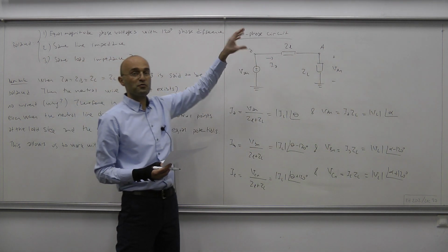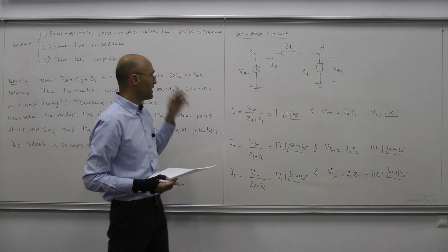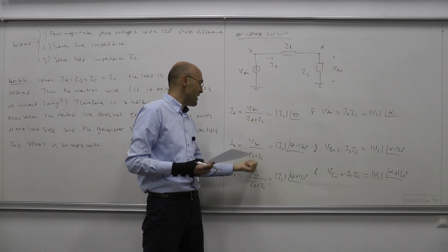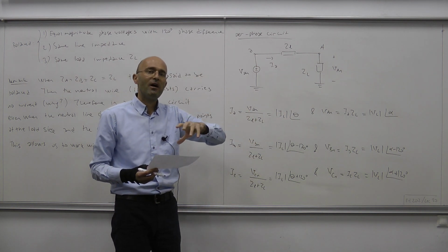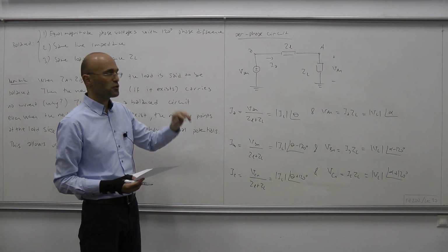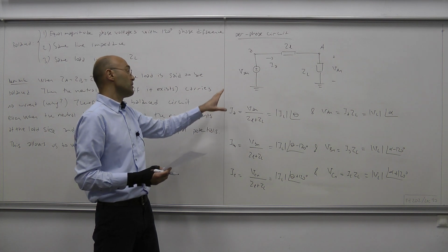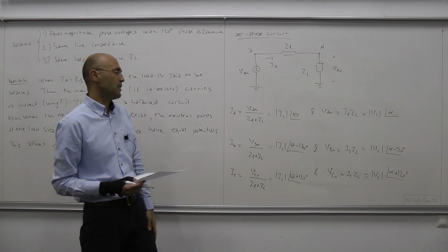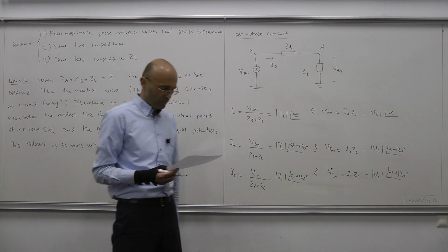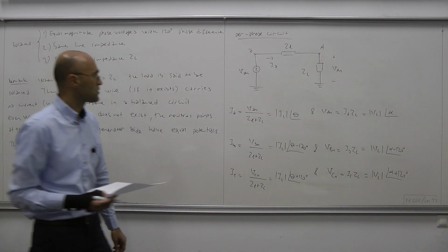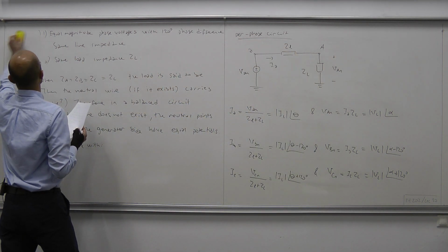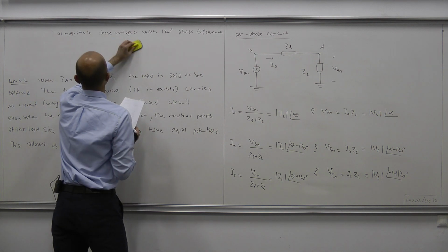Therefore, because we're dealing with a balanced circuit, the balancedness of the source voltages VAN, VBN, VCN will be shared by all the triples, be it current or voltage, throughout the circuit. So the balanced phase currents will have the balanced phase voltages on the load side, and so on. Okay, so let's end this lecture with that simple but important observation.